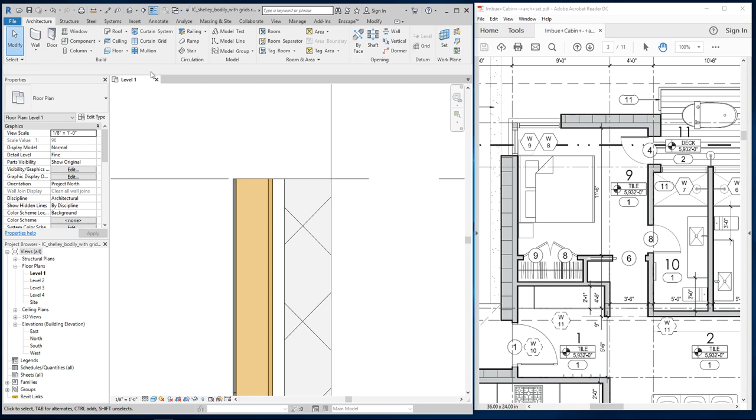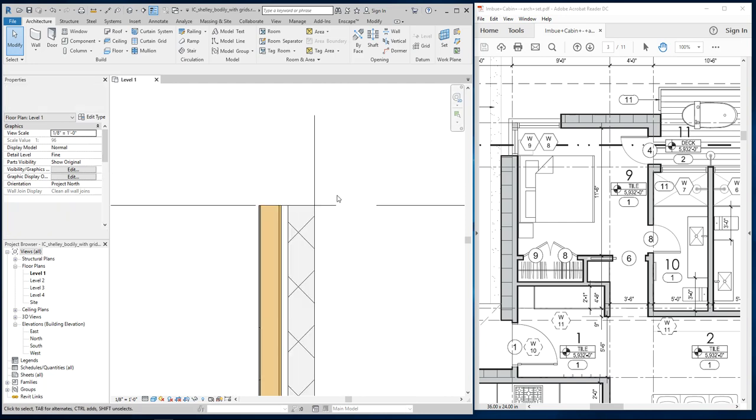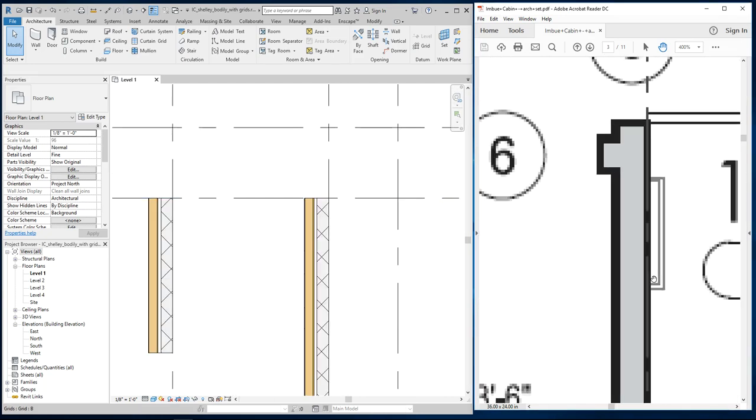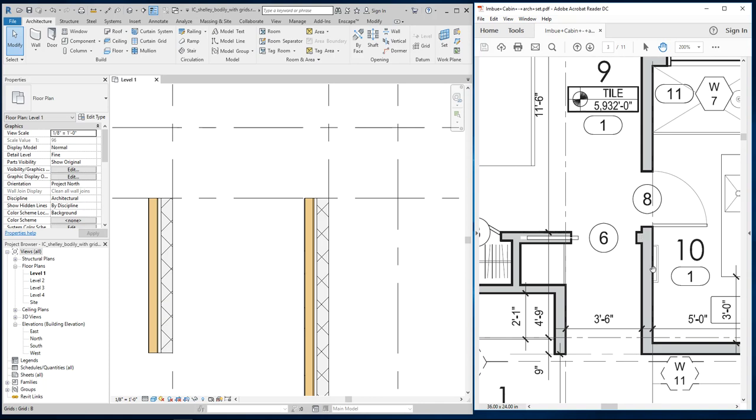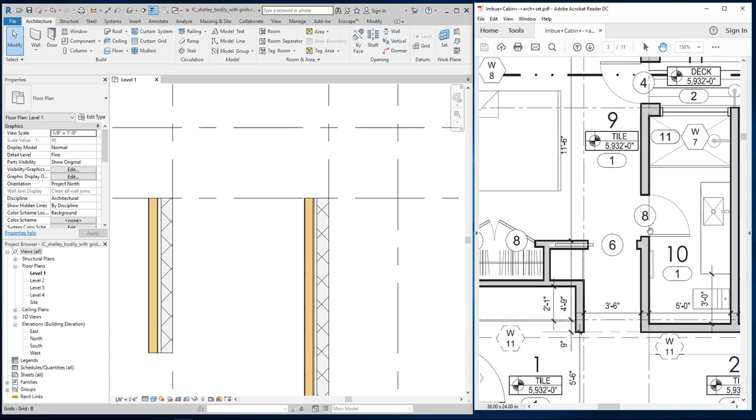Like my halls now on the print say 3.5 inch or 3 foot 6 inches hall. Now they're off by 1.5 inches. Right, when I measured. So that's normal? Because of the walls you made us build. Yeah, probably. They may have. I don't have the wall types on this plan. This looks like a 2x4 stud wall, and this right here looks like a 2x6 wall.